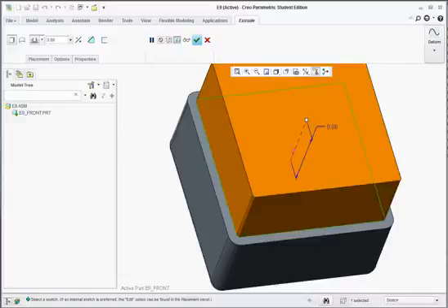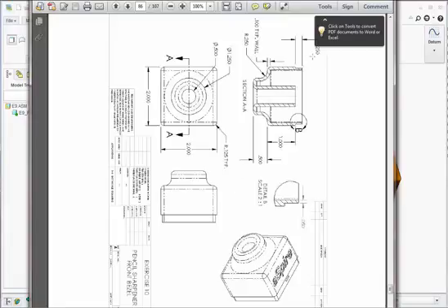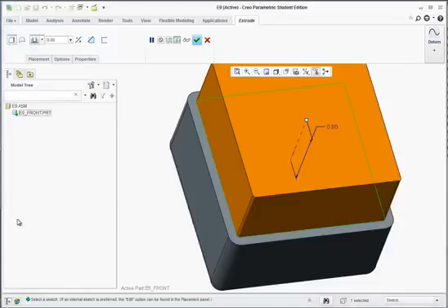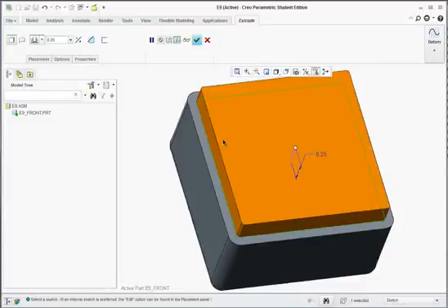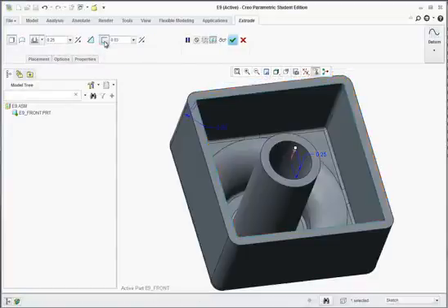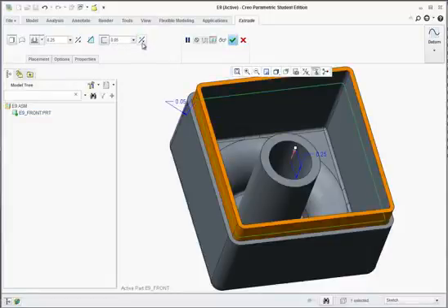Now the thickness of this is going to be 0.25, or the height I should say, and then the thickness is actually 0.05. So let's go ahead and change it to 0.25 for the height. And now let's take a look at a tool here. Right here, it allows us to create a thin feature. So if we click on thicken sketch, we could put in a parameter, in this case 0.05. And we could hit the reverse button right here.